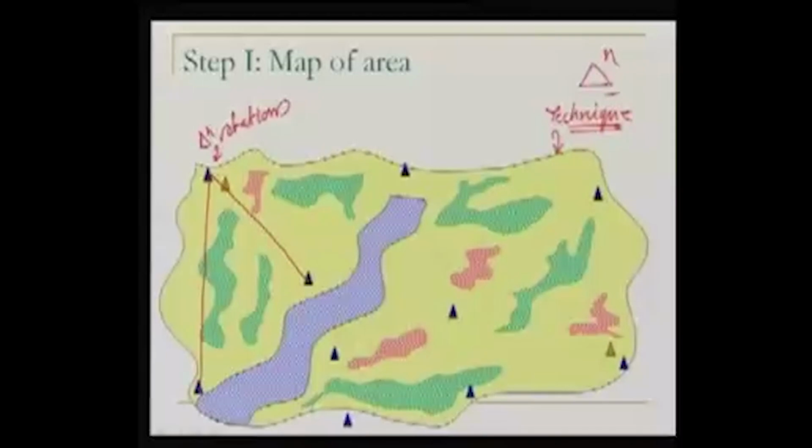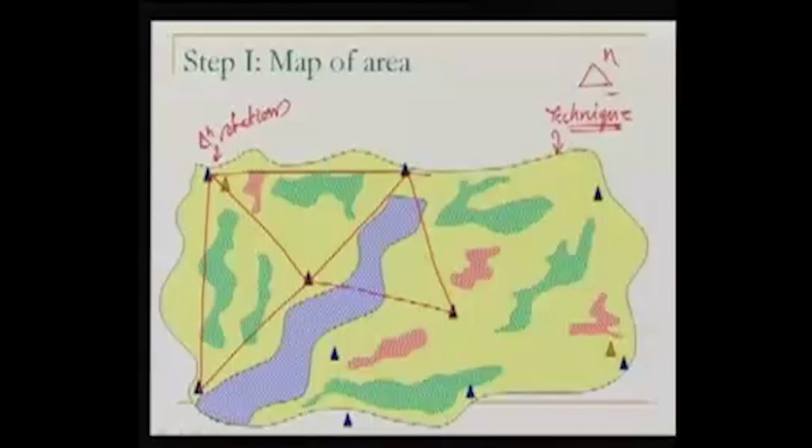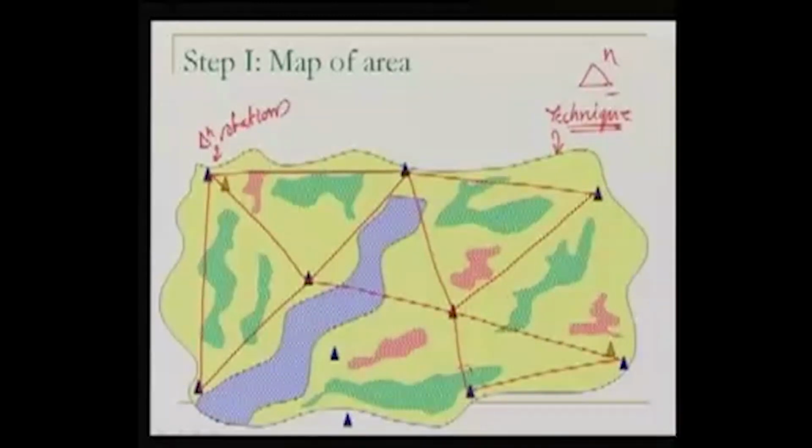We'll measure all the angles which are possible there. We'll measure one length out of all these lengths which is possible to be measured easily. So over here, what we are doing right now, we are forming the triangulation. Right here, we are assuming that the intervisibility is possible. That is why we have taken the line of sight through jungle. Similarly, here also. So that's our triangulation network.